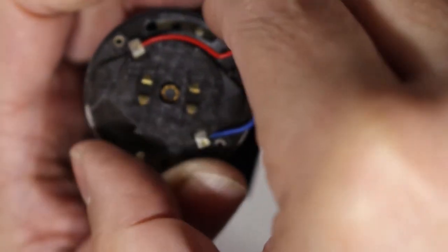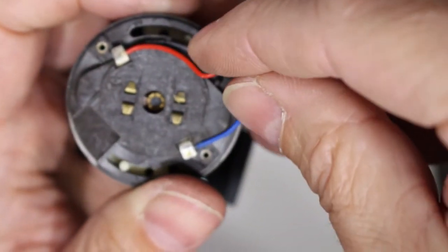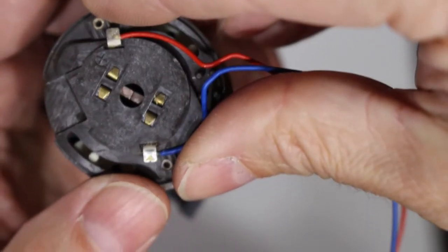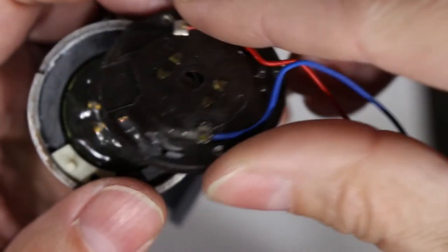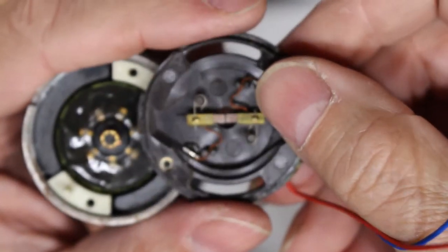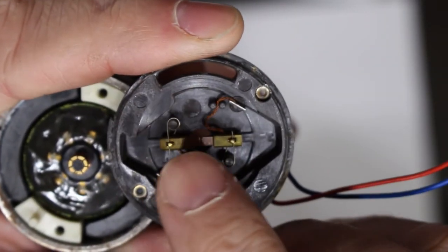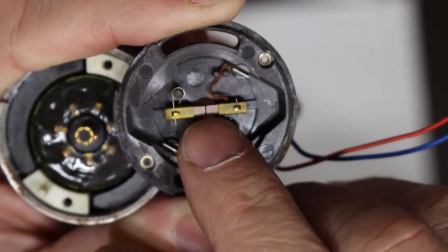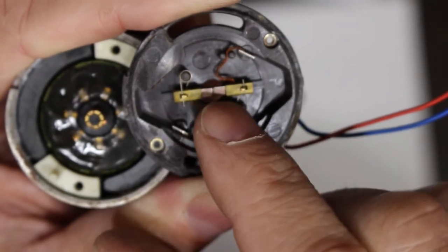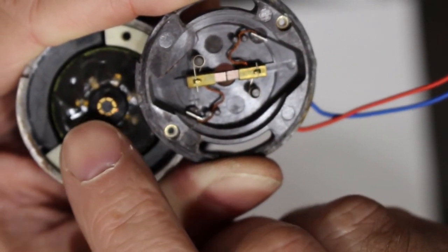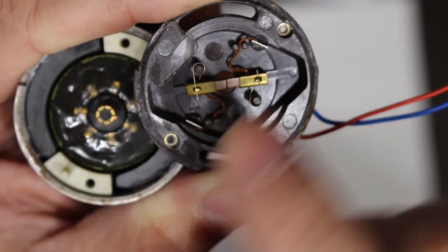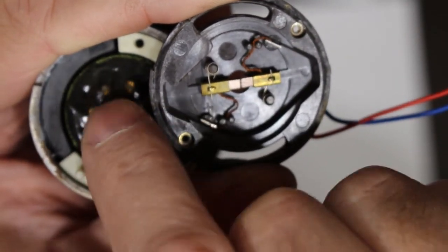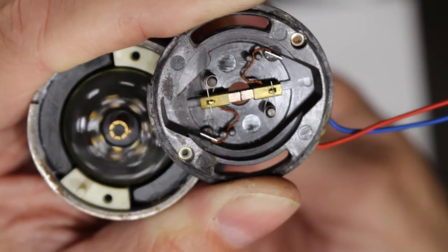And again, when I separate this, this is what happens. Watch, the brushes are spring loaded, they'll pop back into place. There we go. And flip them over. So again, the brushes themselves are spring loaded and they touch up against the side of the commutator and bring electricity from the outside world to the inside world of the motor.